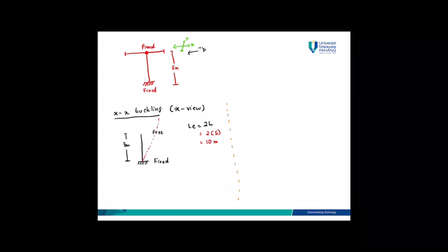And if you look at from Y buckling, it is actually you look from Y axis. So if you look from Y axis, you look at from here. So your eyes will be parallel to Y axis. You look at here, then you can see the brace and also you can see the column. So from Y axis, you can see the column and also you can see the brace that had been attached at X axis.